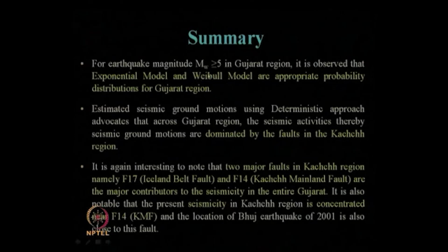Whereas, for earthquake magnitude Mw greater than 5 in the Gujarat region, we mentioned and proved also that the exponential model and Weibull model provide better results than other models. And we have carried out deterministic seismic hazard analysis as well as probabilistic seismic hazard analysis.